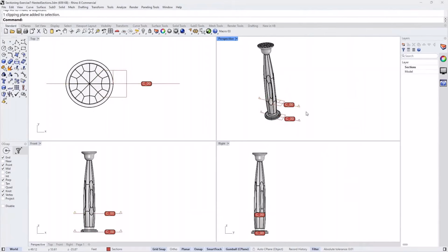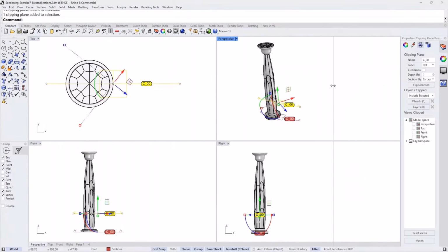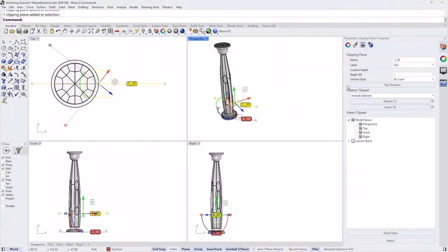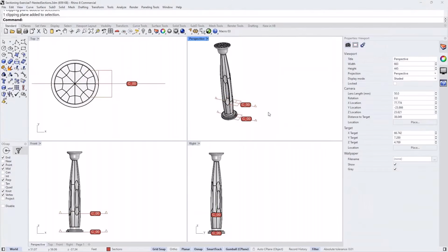If I want to create 15 different sections through my column, I want each one of them to have a unique name. By default, the clipping planes, with the properties updated in the property name here, don't quite register with the list of sections that get managed, and this is why it copies the exact same one. And you will see what I mean in a second.